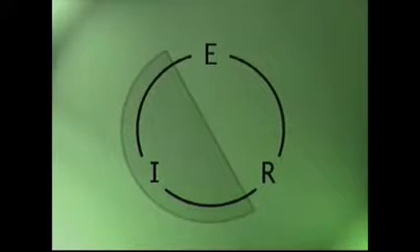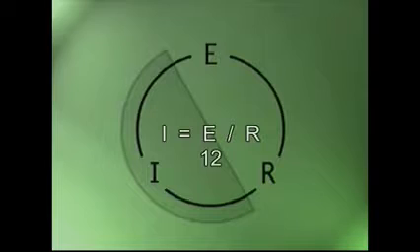Similarly, if you know the voltage and the resistance, you can cover the I and get the formula I equals E divided by R. To do the math, if you know you have 12 volts in a circuit and you have a resistance of 4 ohms, you can divide the 12 volts by the 4 ohms and you'll know the current flow is 3 amps.